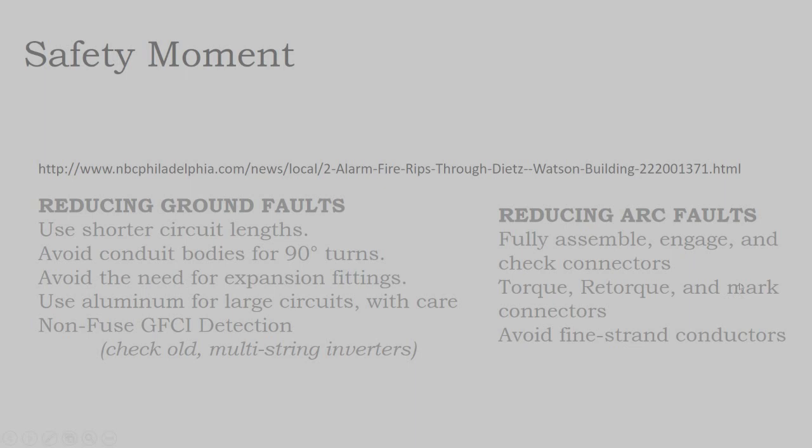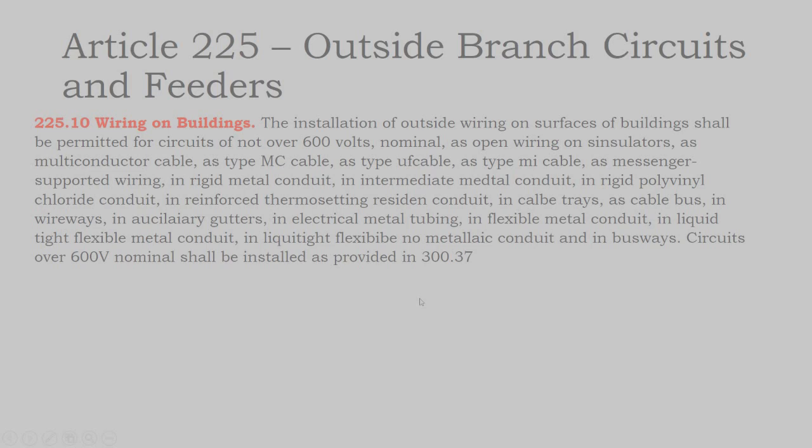Arc faulting, it's more about, are your connectors made up tight and correctly? And then avoiding fine strand conductors. You use stranded conductors in solar, but it's not fine stranded.